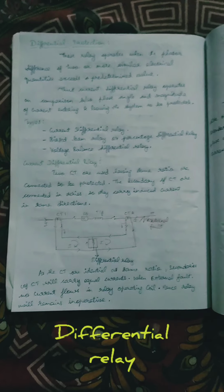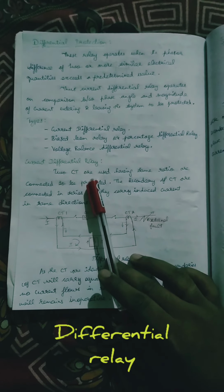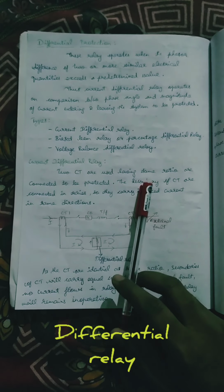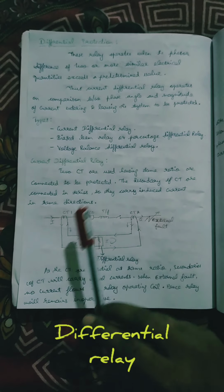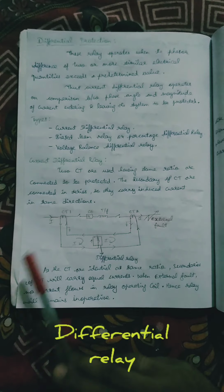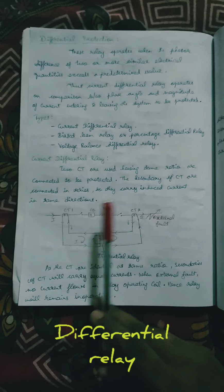The current differential relay is basically the differential between two CTs. In this case both CTs have the same ratio, which means if the CT is 200 amps or 2000 amps or even 4000 amps by secondary 1 amp or 5 amps, both ends, CT1 and CT2, should be in the same ratio. The secondary current should also be at the same level, which means 1 amp for both ends, and 5 amps for both ends.